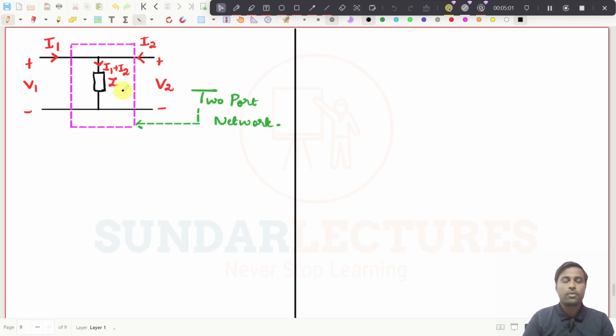Now you see we have taken a circuit like this. This is the first port or input port, V1, and the current is in this direction, and this is V2 and the current is in this direction. This is the output port. This is a two-port network, right? Now if you want to find the Z parameters for this circuit, V1 can be written as Z11 I1 plus Z12 I2, and this is the equation.